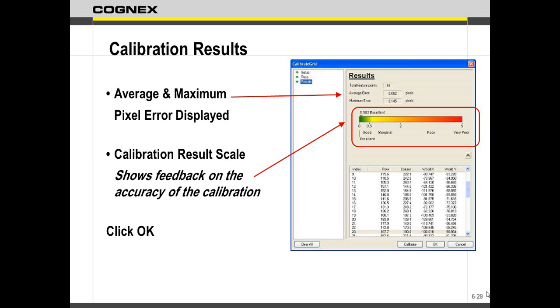Measurement requires relative calibration. What's the other? I gave you a hint there because I said relative. Robot requires absolute. Because if I'm just doing a measurement, where my center point is really doesn't matter. If I measure here, same measurement. Boom, boom. But if I'm doing a robot, I need to know where that position is in the real world. So where I place that center point becomes very important at that point.